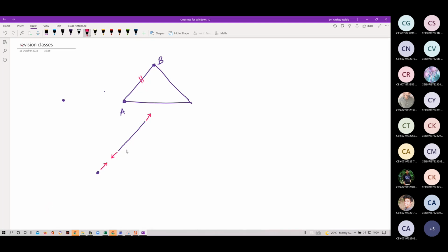Here this is joint A, and this is joint B. The member is being pulled apart. It's in tension. So the member is also pulling the joint in return. When you take a string and pull it between your two hands, it appears that the string is also pulling you.